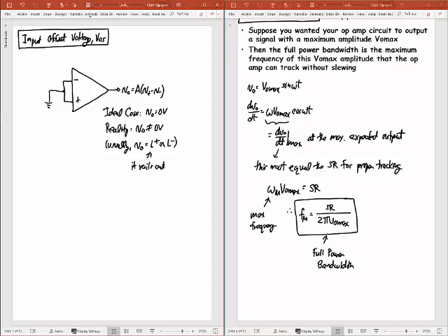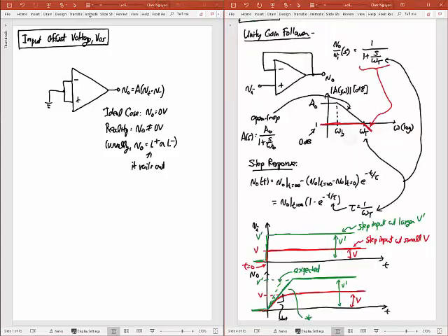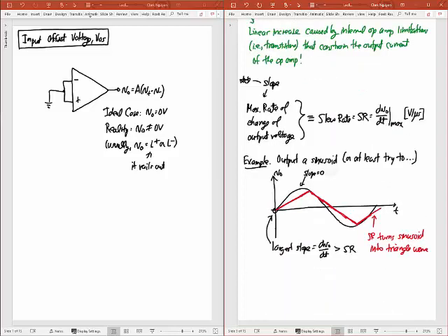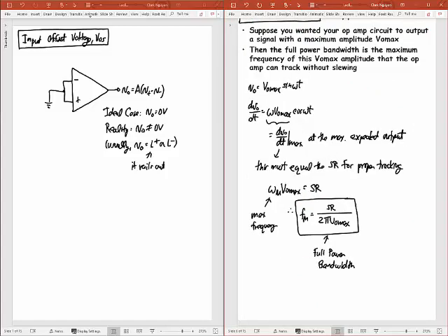Okay, so why does this happen? This happens again because of the transistors inside of the op-amp. In order to really get 0 output voltage for 0 input, the 2 transistors at the input, and so I'll just point them out right here because maybe you'll remember this, this transistor and that transistor have to be exactly identical. Okay? What are the chances 2 things are exactly identical? Almost none, right? There's going to be some finite difference between them, and because there's a finite difference between them, you get this offset in the op-amp. So the op-amp does not behave the way that you would like it to.